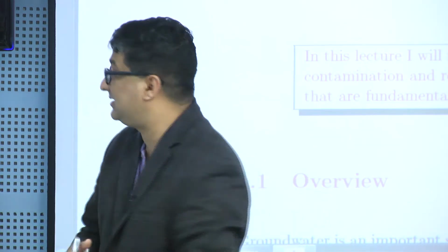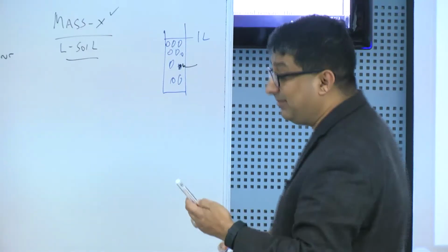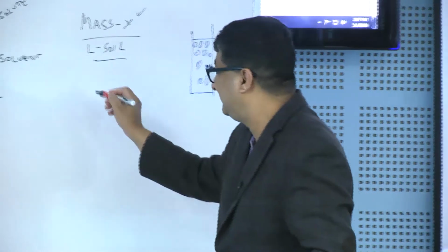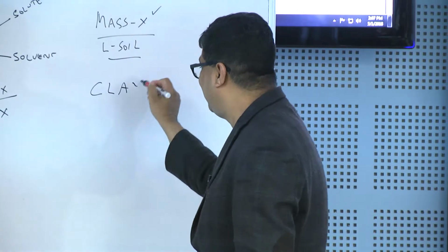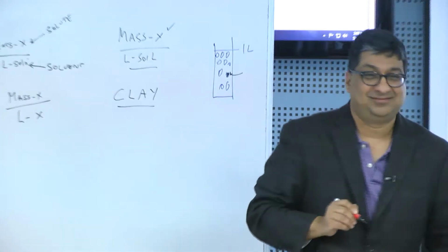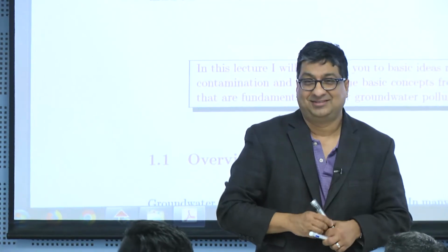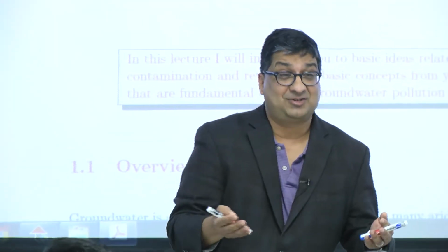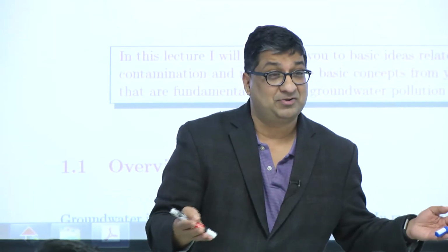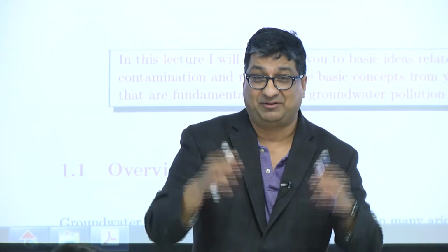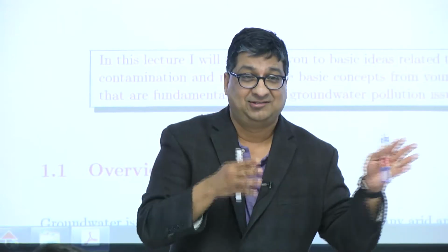The reason there is subsidence is because of clays. Can anyone tell me what a clay is? What's a clay? How can I define a particle and say that particle is clay? Okay, so the way civil engineers have defined clay is using the size of the particles. We say if it has a certain size, if it passes through a certain sieve, that's a clay.